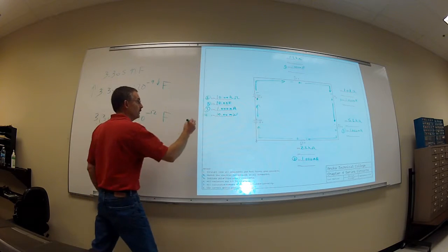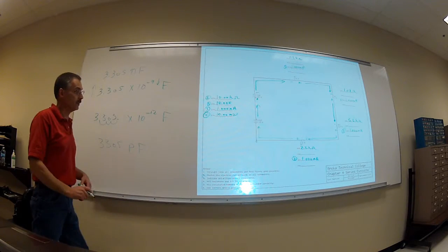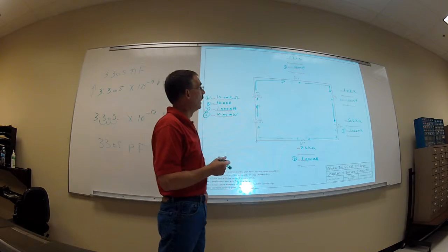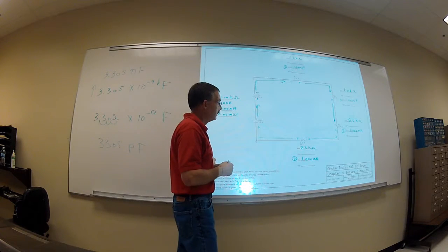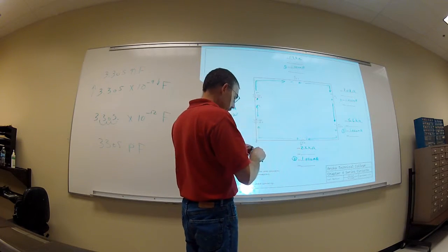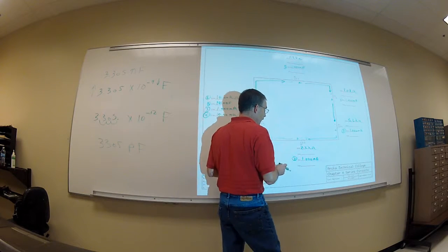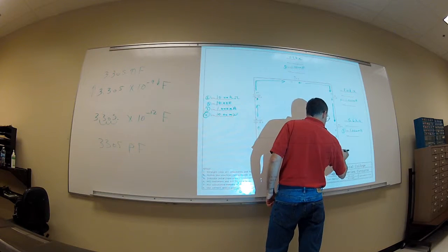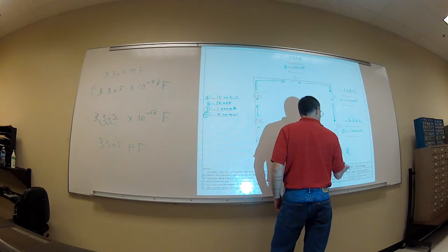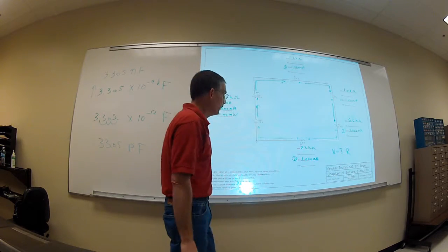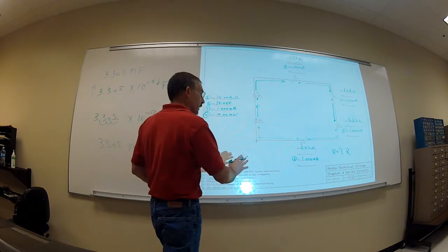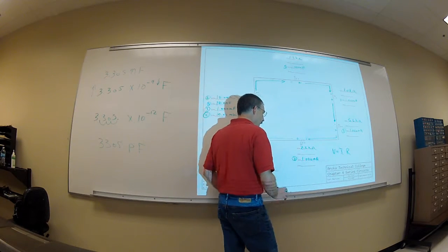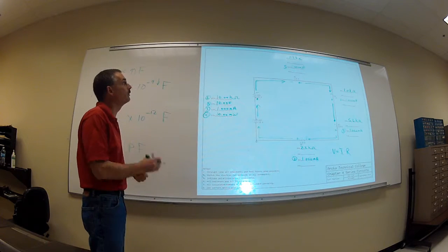Okay, good. All right, now what's our next step? Yeah. Now here's what we call voltage drops. We're going to calculate our voltage drops. Remember, voltage drop is equal to I times R, so they're just IR drops. And we haven't been using any polarities, and we never will be putting polarities on our voltage drops. So what do we get for some of our voltage drops?